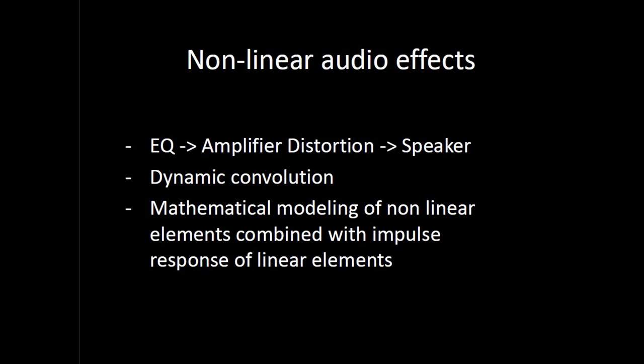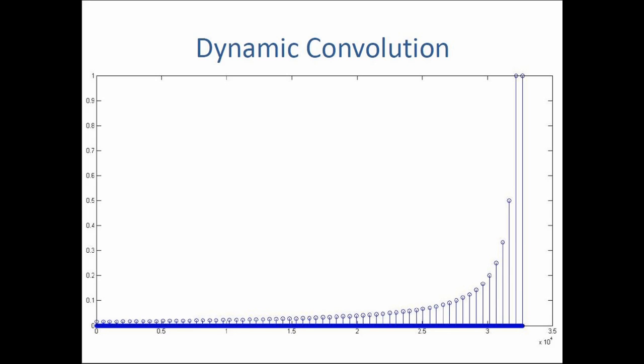These samples turned out pretty well, so I wanted to see if I could use a variation of this method to model effects that were not linear. The system I chose was a guitar amplifier. I used a method called dynamic convolution, which basically looks at how a system responds to an impulse at different threshold levels. Here are the impulses for 6 bits worth of sampling, or 64 levels, and what it sounds like.